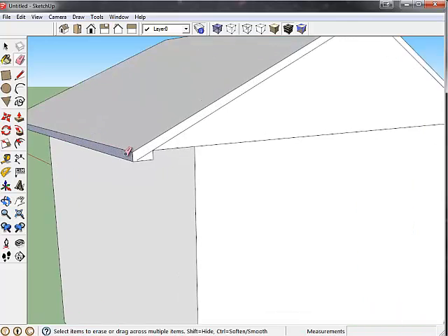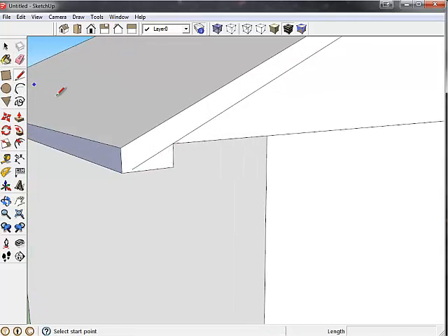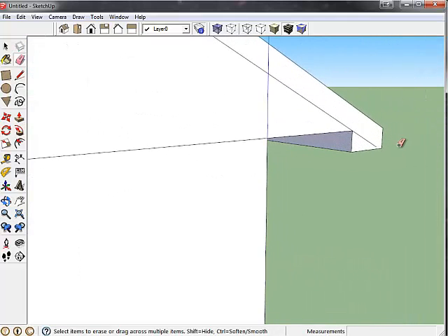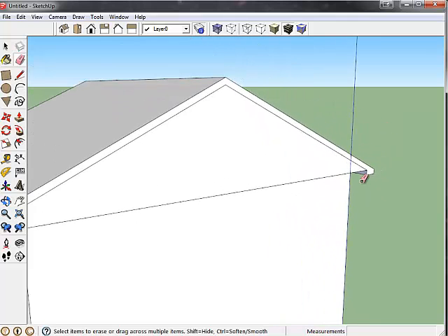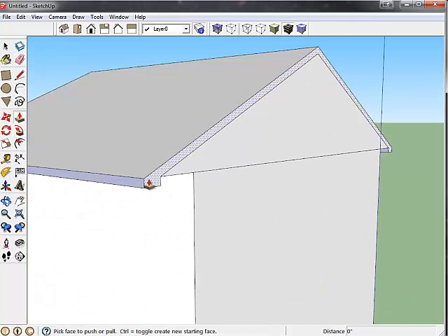You'll notice this side is slightly different because we already pulled this front down. So when you offset 4 inches from the top arch, it gets like this. Not a problem. Just connect the top edge from here to here. Delete the middle line, and then delete this line, and that'll give you your profile. Same thing over here, cross and down, or just delete this line here. In doing so, that will give you the profile you want, so you're able to push